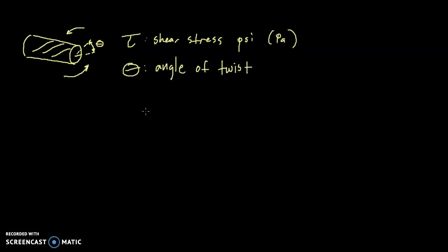So if you're a structural or mechanical engineer and you're designing some type of drive shaft or structural member that has to resist or transmit torque, you have to make sure that it's adequately large enough so that it doesn't shear apart and break, fracture due to the stress within an allowable factor of safety. We also want to make sure that it doesn't twist too much. That can cause like a backlash in a drivetrain. So we want to minimize these two things. We'll typically be given an allowable shear stress and an allowable angle of twist, and we might then need to size the cylinder that's needed.